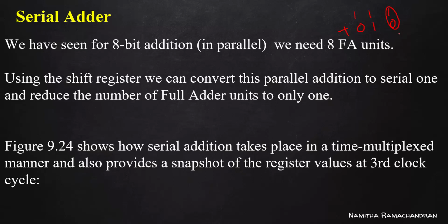For adding this, we can use one half adder. Sometimes it will generate one carry. That carry comes over here, as one carry bit. So with 3 bits in total, here we need to use one full adder circuit. Again, this addition sometimes will generate a carry. That carry comes over here, and here it forms the 3rd bit, so here we need to use a full adder.